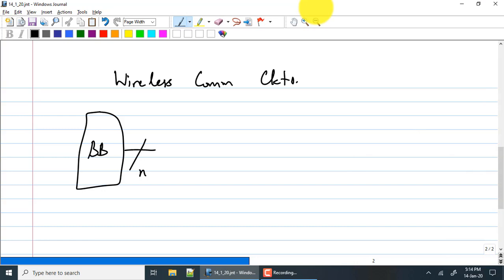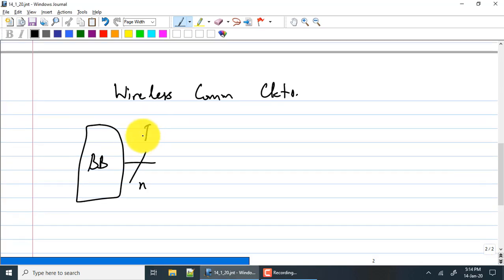So you need to take this data, and because the wireless channel is a shared channel, you have to somehow separate users. You have to separate multiple users because several sets of people are trying to communicate with each other. Maybe in the next class or after a few classes, we'll figure out the different ways in which you separate different users. But for now, let's assume that they are separate frequency. That is the easiest way to do this. So each user uses a unique frequency. Now the data itself will have a certain bandwidth. So let me call that some baseband bandwidth. The data occupies minus FBB to plus FBB at baseband.